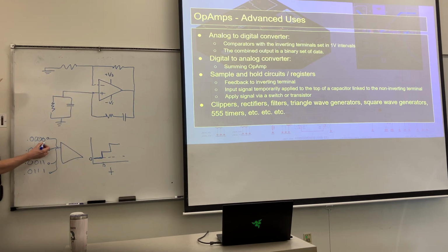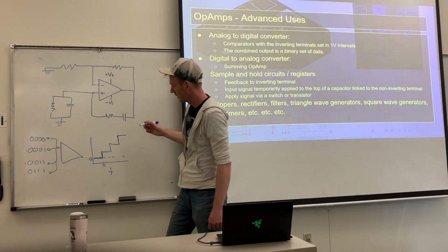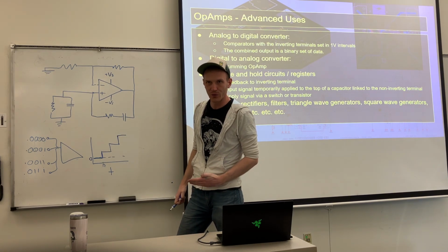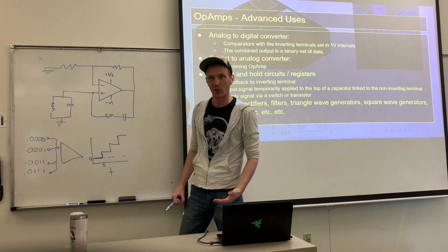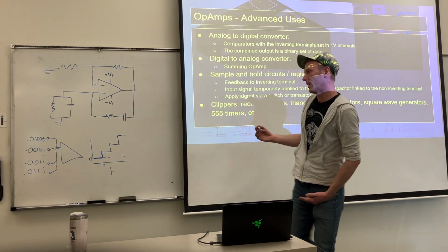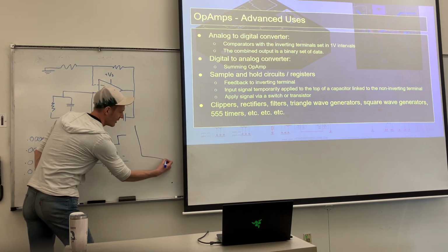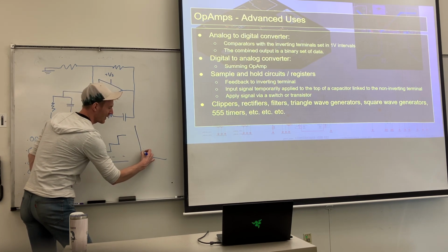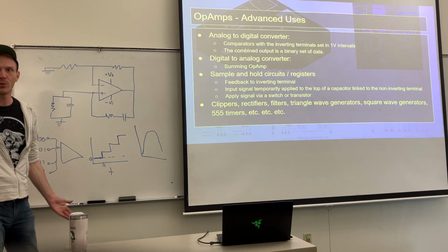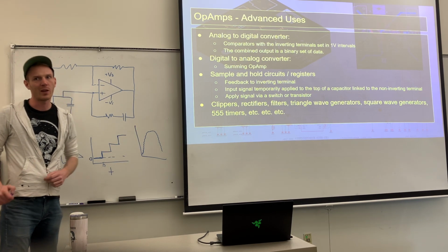For the third one, you have 0, 1, 1, 1. Now we have 4 times. Well, if you have this in incredibly tiny amounts, say instead of 4 bits, we're talking 256 bits, and if you control the timing correctly, you can have incredibly tiny steps going up and up and up, and then down and down and down. And then you take a filter, and it gets a lot smoother. But most of the time, you can make these tiny steps so small that it doesn't matter.